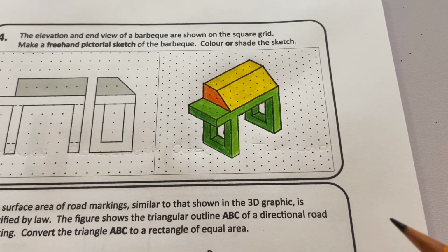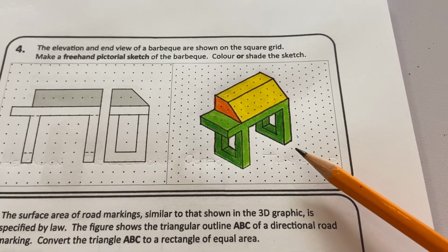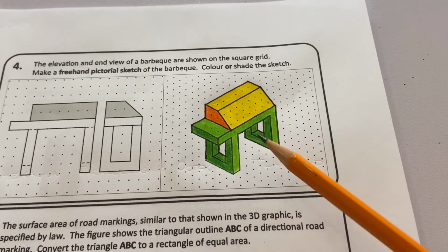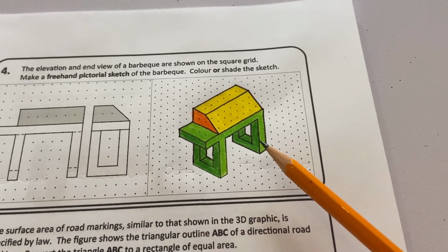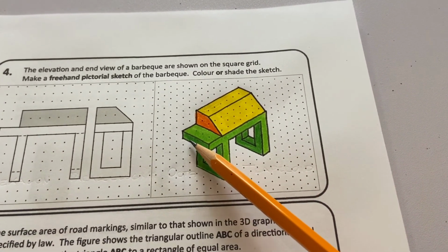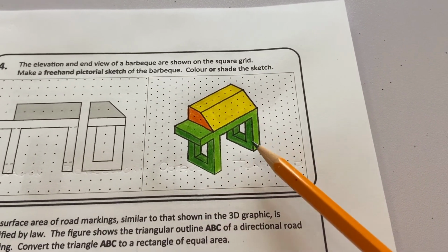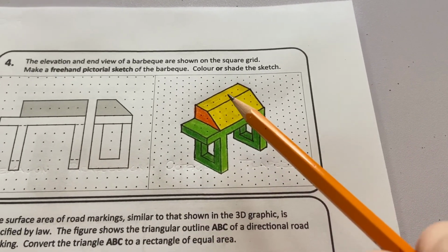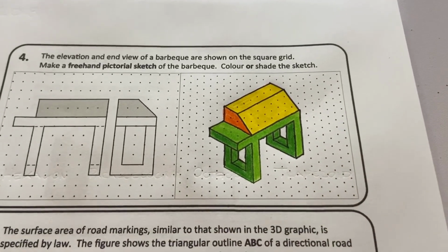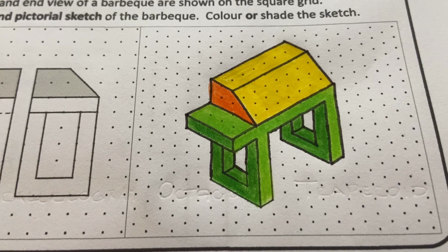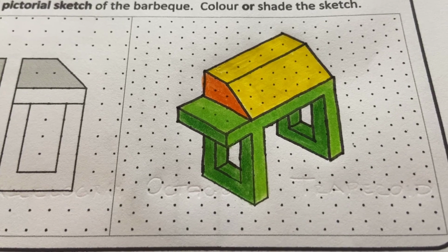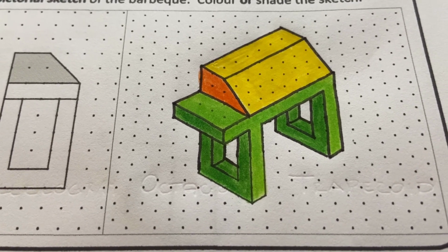When applying shade to the drawing, I have assumed that the light is coming in from this direction here, which means this surface is getting light, whereas these surfaces here are in shadow and shade. So these are coloured in dark green, the internal detail here of the legs, this area here and this surface here. Whereas the front surface here is in brightness, so it's a lighter colour. Likewise, this is coloured light and this here is a dark colour. When you're applying colour and shade to a drawing to improve its appearance, assume a direction of light, think about what's going to be in brightness and what's going to be in shade, and colour accordingly.